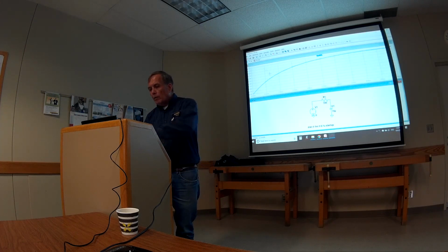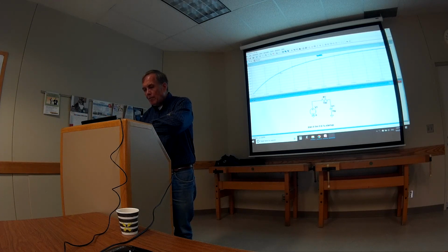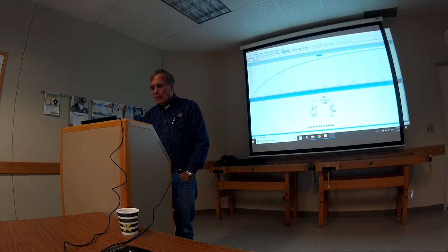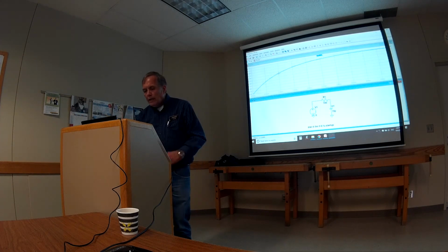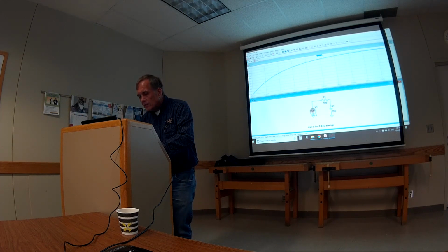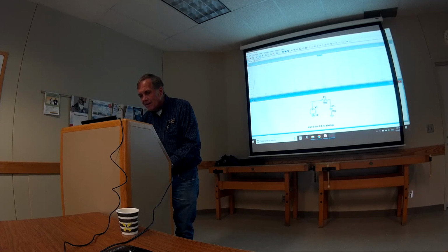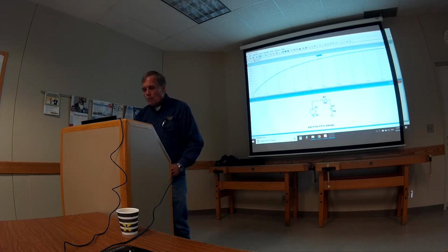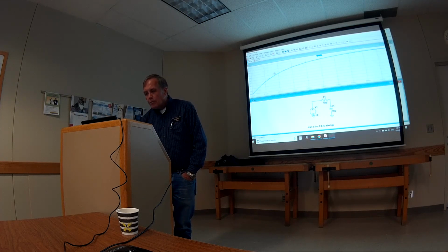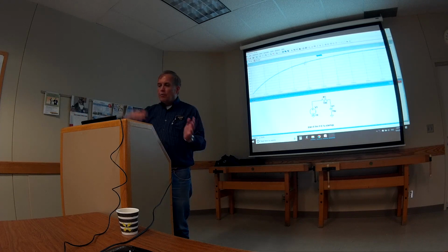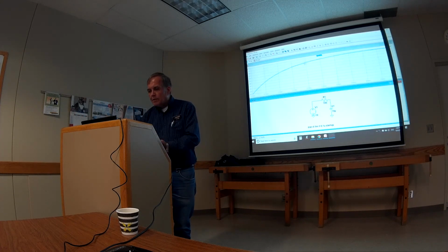So we look here at 1 millisecond, and there we are at 3.2 or so. You know what? If I change this voltage to 10 volts, then we'll read it off directly. So at 1 millisecond, we got 6.3 volts. Now one more time constant, so at 2 milliseconds, it's 62% of that difference again. So it's up to whatever.